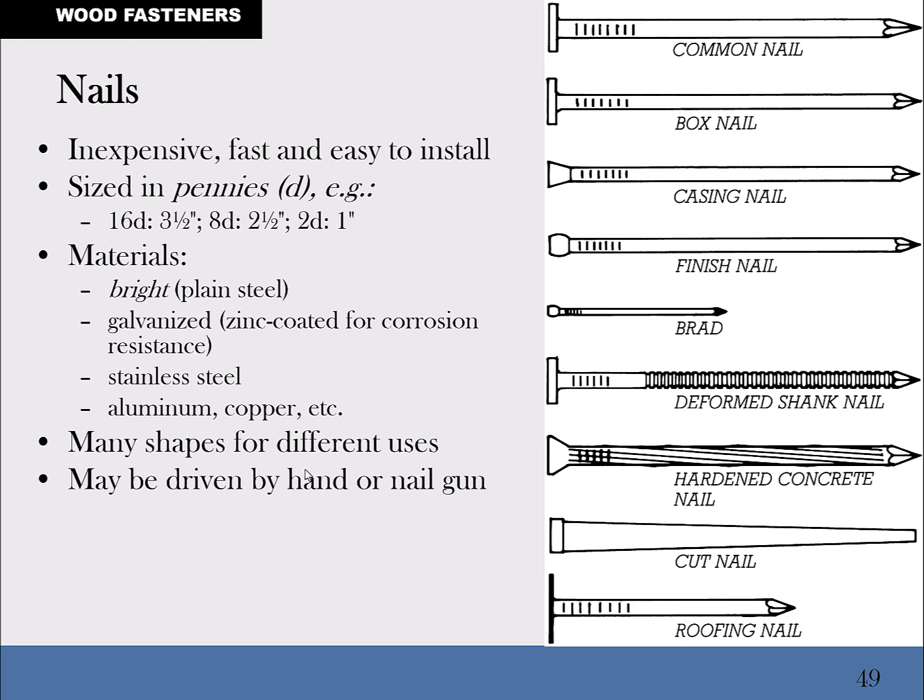I just want you to understand that the higher the number, 16D is certainly a longer and a heavier nail generally than a 10D nail, which is 3 inches long. So 16, larger the number. Now that D, we say 16 penny nail, and why do we have the D? Because it used to be a 16 denarii nail, and now we've decided to convert to a different currency, but we still have the D, but the D came from denarii.